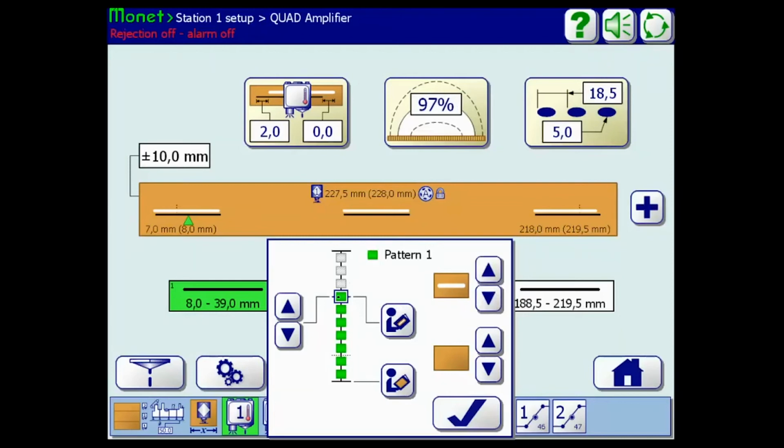Now, I don't actually have a quad amplifier hooked up to this pattern one, but this would allow me to fine tune that peak gain LED, or wherever that top LED is showing up, whether it's 7 or 8, with these adjustments here. So if I learned my glue and it was originally at the 7th LED, but then after running for a little ways, maybe I turned the pressure down just ever so slightly, and my LED dropped from number 7 to number 6, it went down by 1, I could use this glue sensitivity adjustment to bump it back up to number 8.